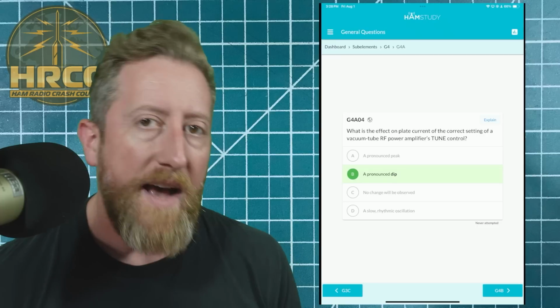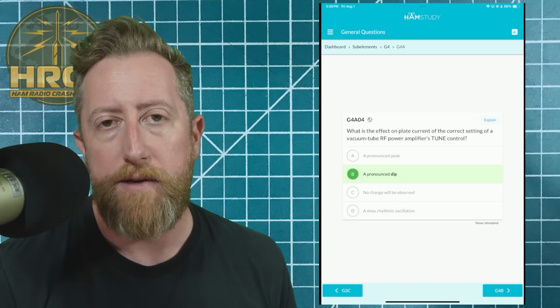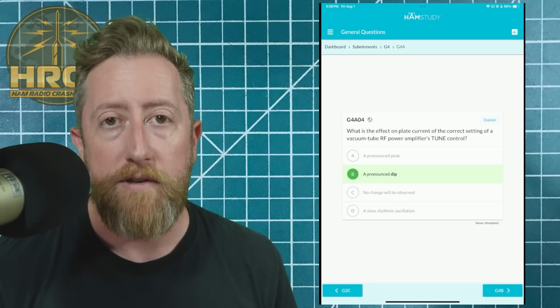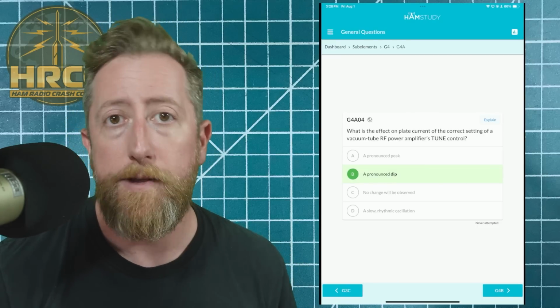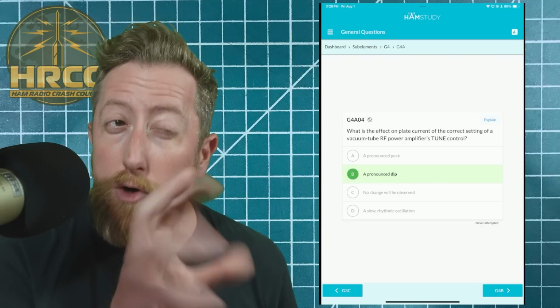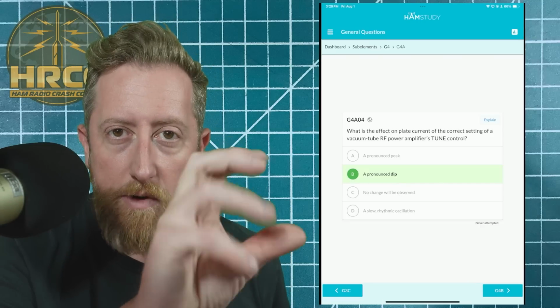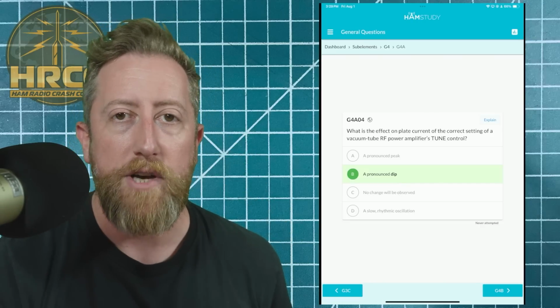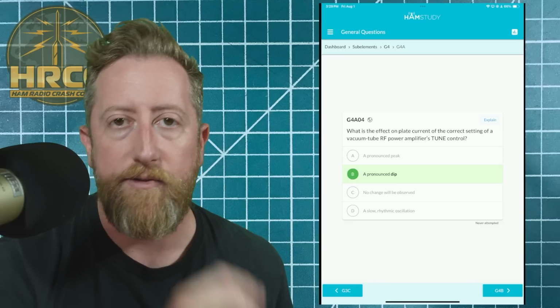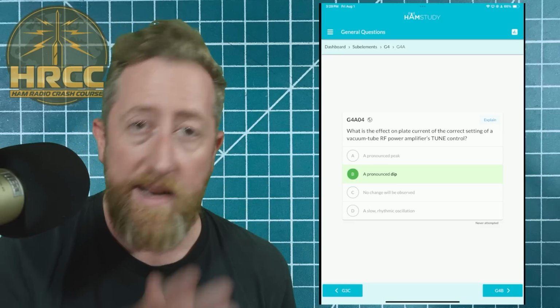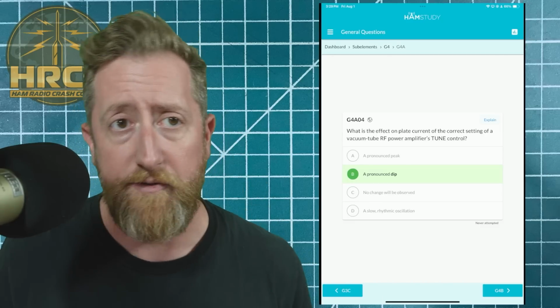Well, so kind of yes, but also the amplifiers we use in amateur radio, some of them still use vacuum tubes. They're available cheaply, and they work just fine. There is a bit of a tuning process to them, though, and you literally go in and adjust a tuning knob to adjust the grid and the plate, kind of back and forth until you get it zoned in, and then it will effectively amplify your signals.